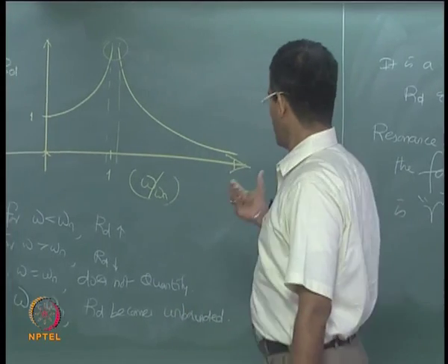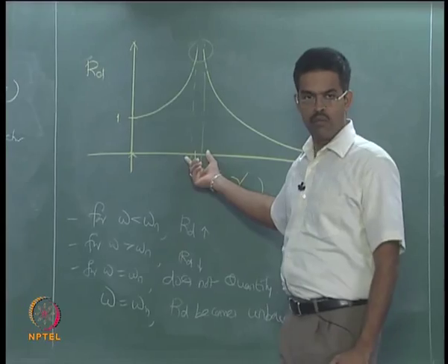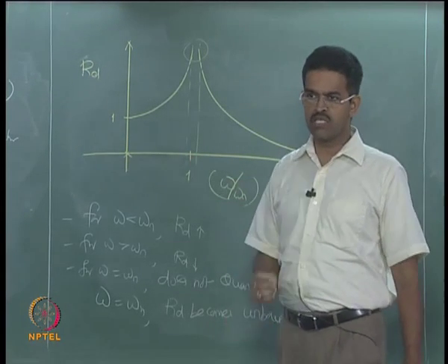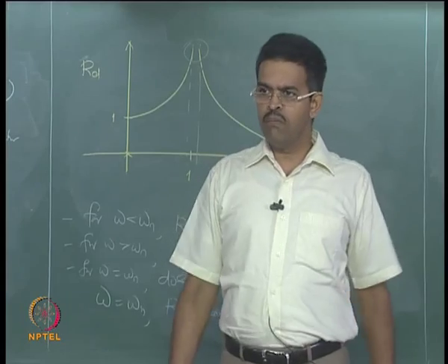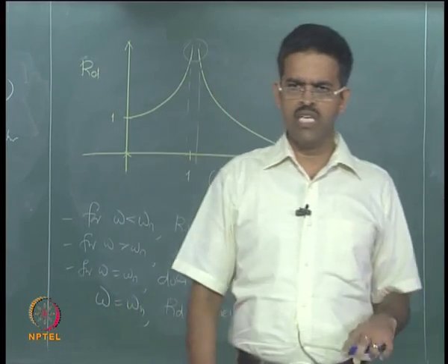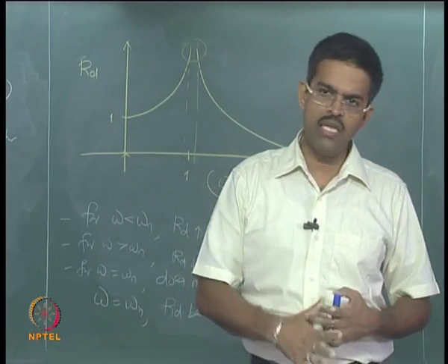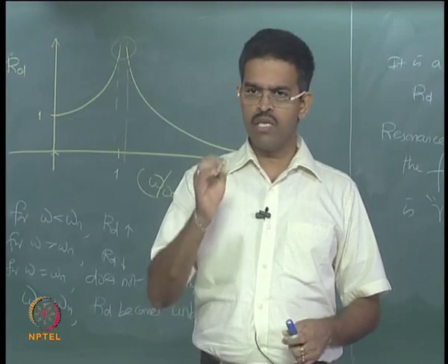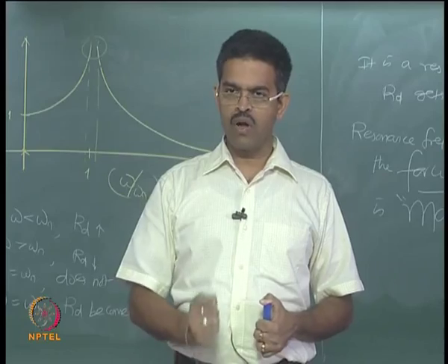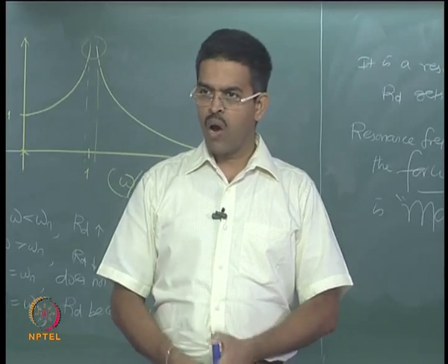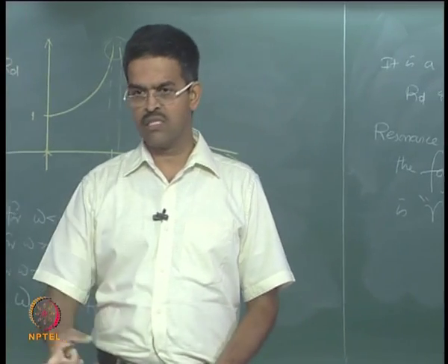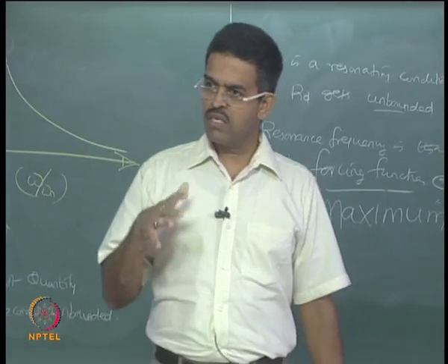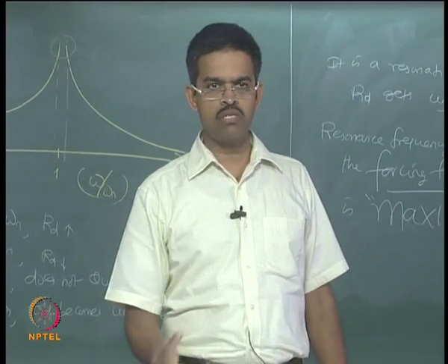Therefore this band will not actually bother me much in dynamic analysis of ocean systems. It is because of this automatic and inbuilt reason that offshore structures generally do not fail at resonance, generally they will not. But even at any one instant of time, if resonance occurs or sets in, how the system escapes from resonance I will discuss in the next lecture. Then you will convincingly agree with me that resonance need not be looked upon in offshore design at all.